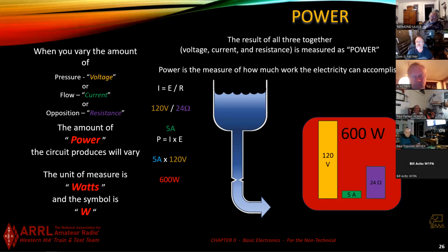And you could do that for any of the appliances in your house, right? In other words, the appliances are rated at like 1200 watts, like a stove. And you use the 120 volts, you can actually figure out how many amps that thing's going to draw when it's powered up. That's a practical use. Al, when you did your solar system, did you have to do any kind of capacity calculations when you sized that thing?